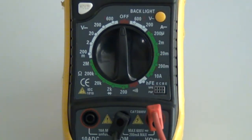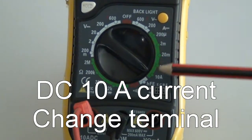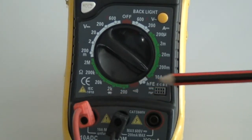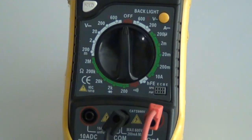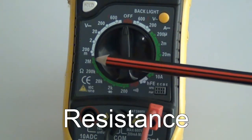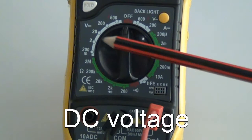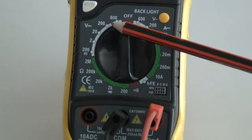We also use these 2 terminals for most of them, but if we select the 10 ampere choice, we have to use the other terminal, which is on the left hand side. This left hand side terminal is used for this option only. If we continue going round, we see resistance, and we can choose between different options. We use these 2 terminals, and finally we can see DC voltage.